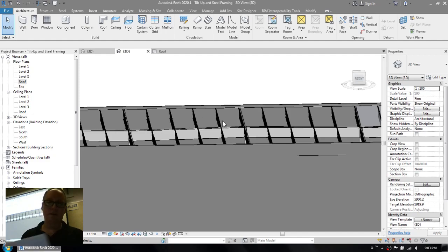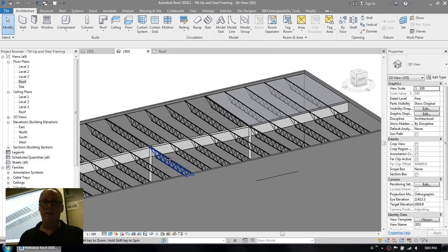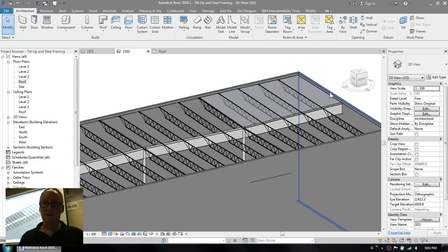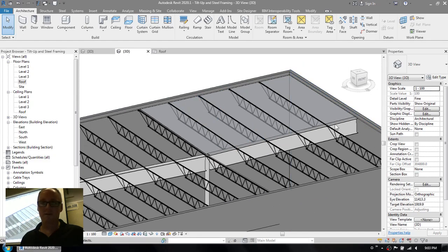We're going to be talking about the massing tool set next week, and you can see this gray toned thing in here. This is going to allow us to skin the roof right onto this plane, which is defined by following the tops of these joists as they warp, because each one of these joists is at a slightly different slope. Trying to model that roof with the regular tools, impossible. Using the massing tool set, it's actually a total piece of cake. So for these super stupid, super garden variety tilt-up structure buildings, they do provide some geometric complexity.